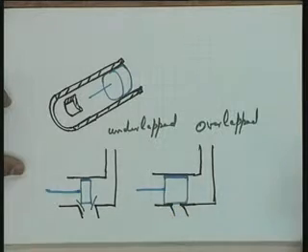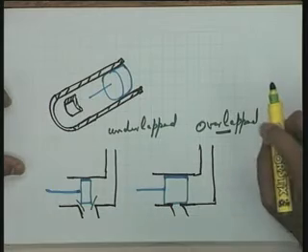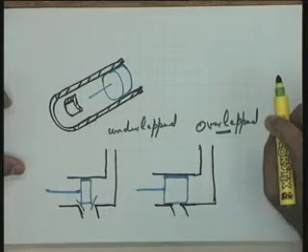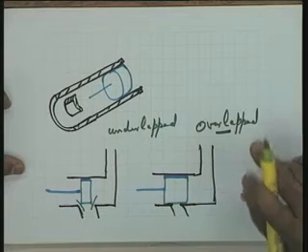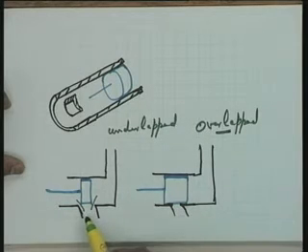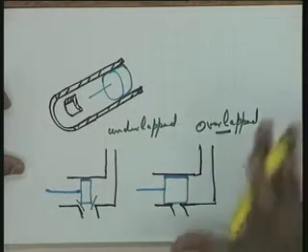You will like that the motor comes into action as soon as there is a small movement of the spool, which depends upon the error in the system. Therefore, overlapped valves are normally not used in high precision control systems, because of the inaction state. Now underlapped valves are used, and they do work appropriately, as will be seen.